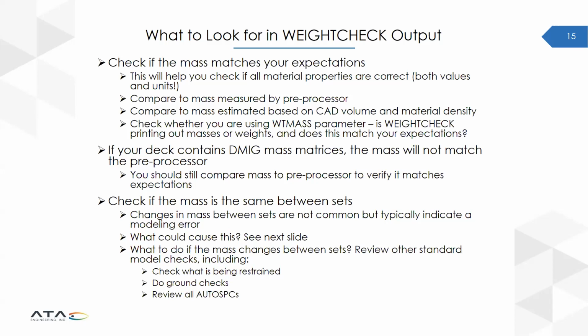So if you use that parameter, WEIGHTCHECK reports weight by default. Just to reiterate, make sure you know whether your WEIGHTCHECK is in weight or mass. That's pretty much all there is. Just be aware of how it works, make sure you know whether it's mass or weight, and then make sure you use that 1/g scale factor if you're using it.